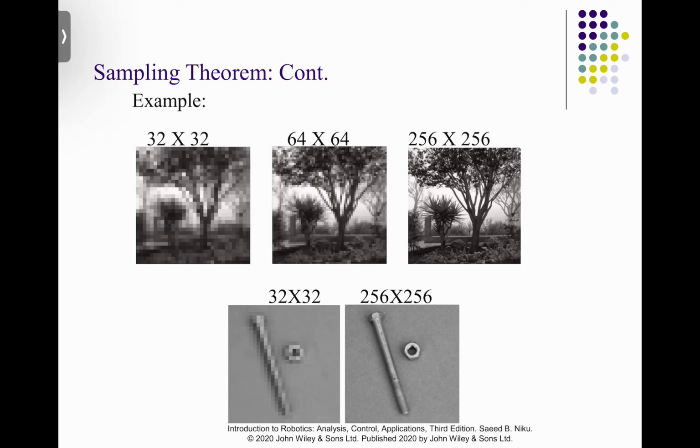What that means is there is a high likelihood, because of the random sampling, that I could capture the slowly moving component of the signal, and I can capture the fast moving component of the signal. That is the fundamental principle of compressed sensing. What does compressed sensing mean? Compressed sensing means that you can violate the Nyquist criteria if you randomize your time samples and capture the signal.